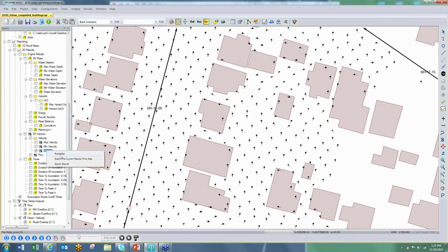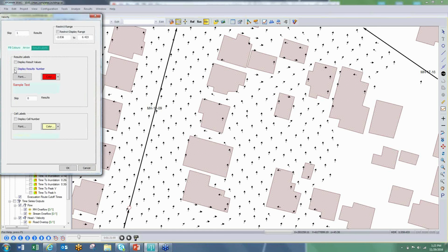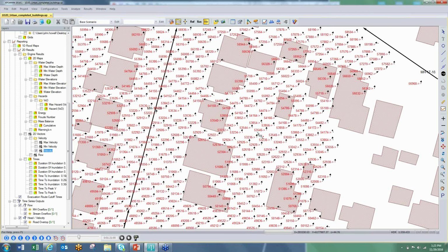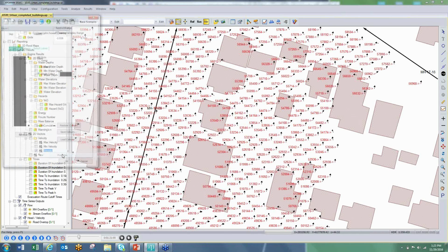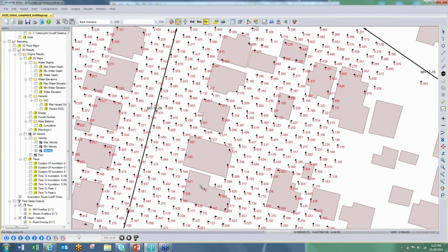If I have an area of recirculating flow, are these high velocity areas of recirculation where that could pose big problems, right? And it's going to give me the velocity value at each one of those points. Sorry, that's our value. It wasn't 2,000 meters per second. It's more like 0.243 meters a second.